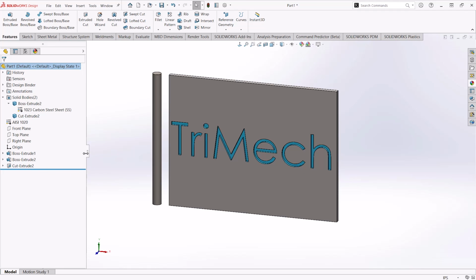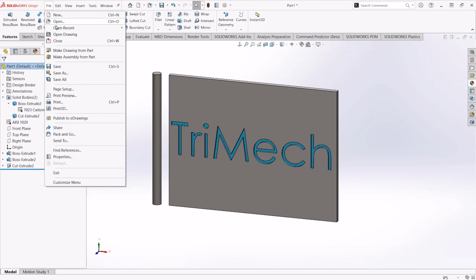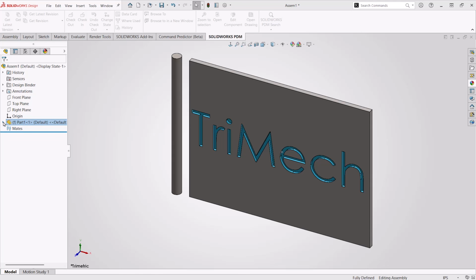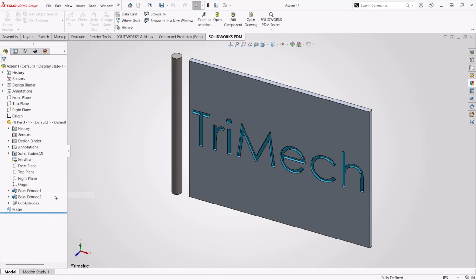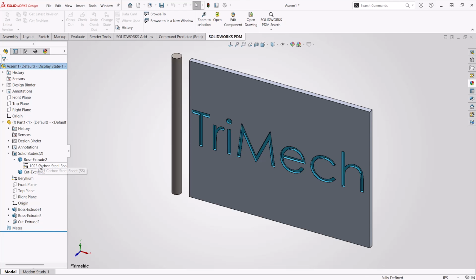We can also change appearances in an assembly. To do this, we would go through our feature tree and right-click on the material selection for the part to change it to a different material. One thing to note is that we are not able to change material for things in a solid bodies folder.